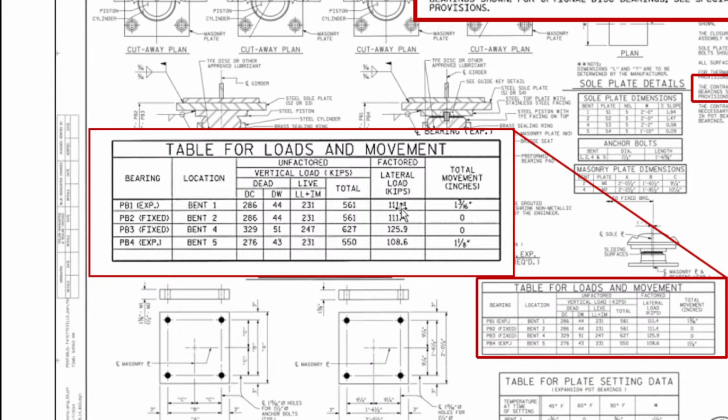If we say unfactored, we have yet to multiply the load factor. When we say factored, we already multiply the load factors and sum it up, total it up. So add all of the loads. That is what we mean by factored here.